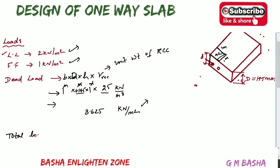So total load, after simplification you will get 3.6 and again 3, maybe the value will be 6.625 kilonewton per meter square. Again factored load. While explaining the concept I told you, for the limit state of collapse in concrete you take 1.5 times the total load, that is 6.625. That means we are taking an extra safety factor, that is 1.5 times.